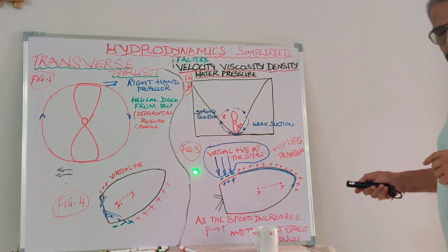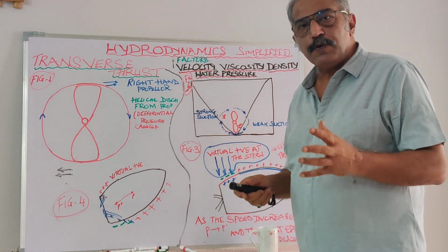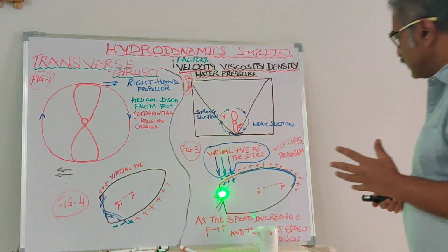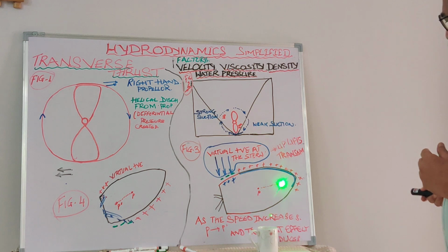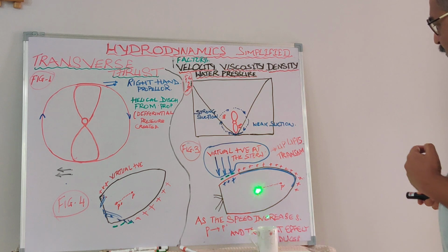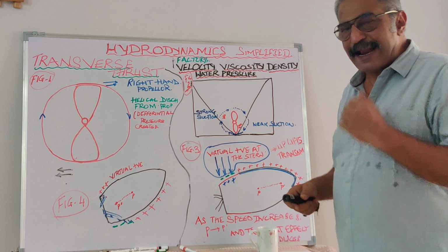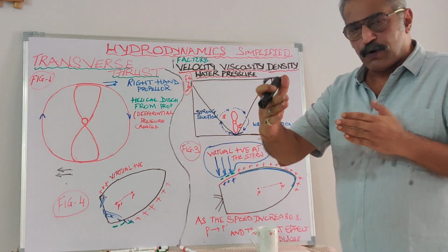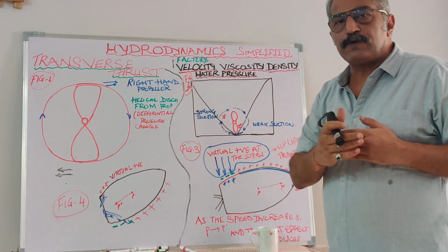Same thing I've depicted here also. The same thing I've tried to simplify here. Now you see here, the vessel is going ahead. That is when she is starting from rest, Newton's first law of motion. When the vessel is starting from rest, we will find, as I said earlier, the pivot point goes forward from the center. That is, when the vessel is at rest, till it starts moving ahead, the pivot point goes forward, and it settles down approximately 1/4 of the length from the bow, because of the water pressure it is getting on the bow.